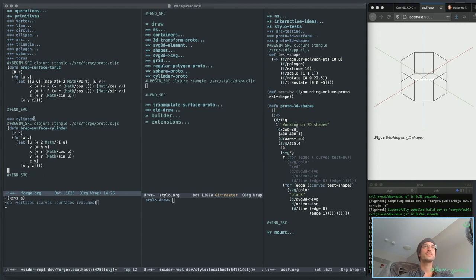which actually, the kind of cool thing too about geometry is there's so many different ways to define all of these things. In this case, the cylinder is nicely defined directly by, you just remap u and v to their domains. So the height v goes from 0 to 1 scaled by the height, and u goes from 0 to 1 scaled by 2 pi, because u is going to be traversing a circle.